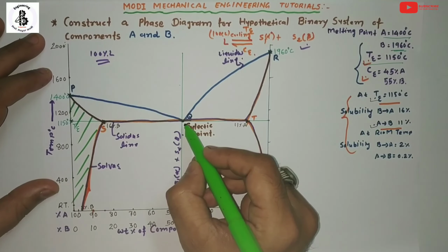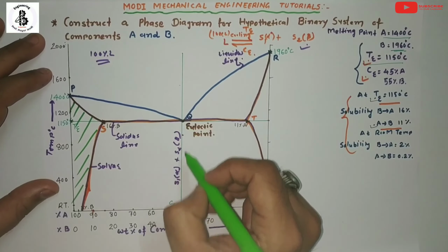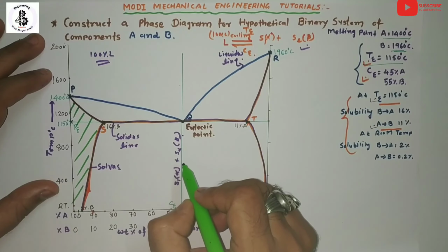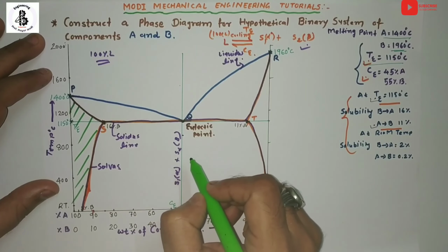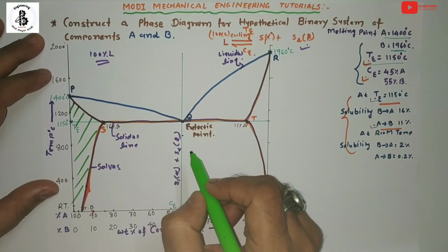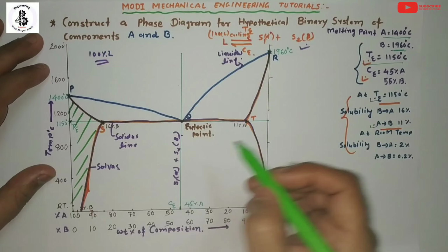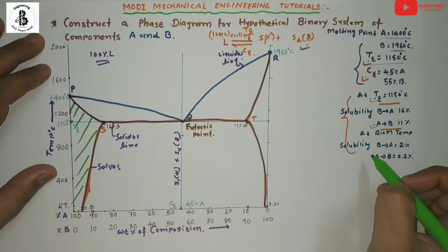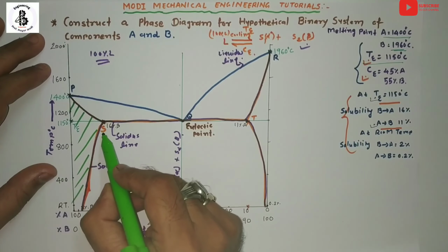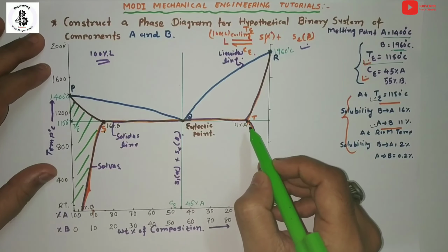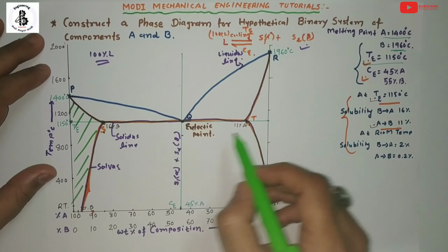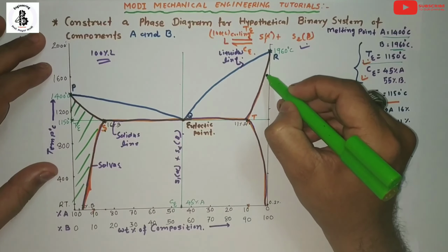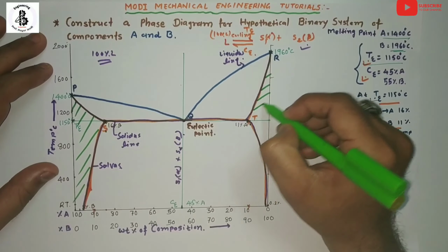In the case of a eutectic it always forms two solids, but this diagram is related to partial solubility. So both metals A and B have different conditions with respect to different sets of temperature and composition. According to the points S and T, there is solubility from both ends, left side and right side, which have a solubility region.